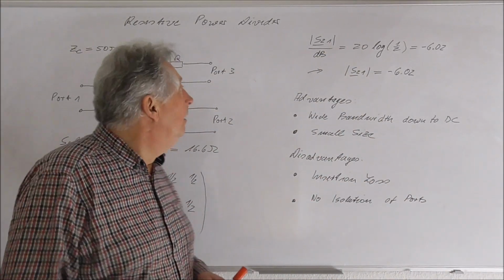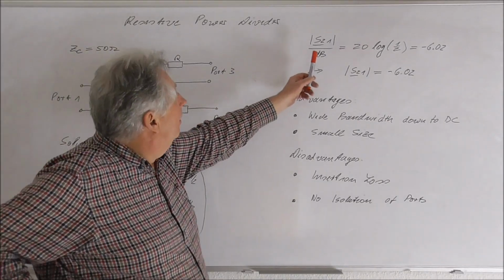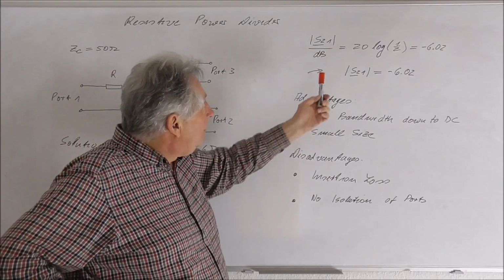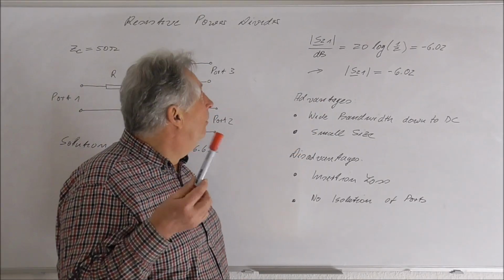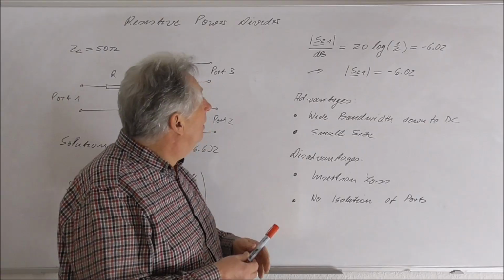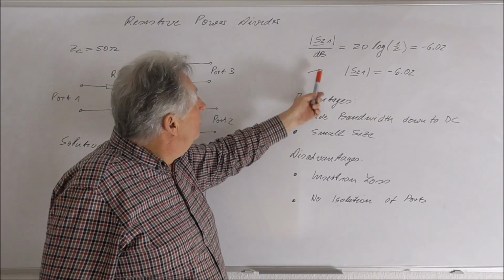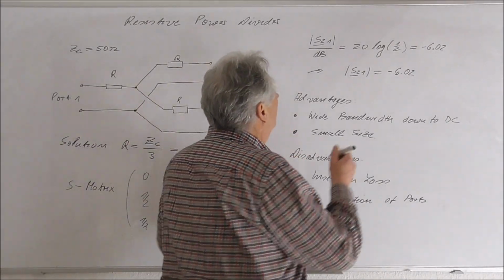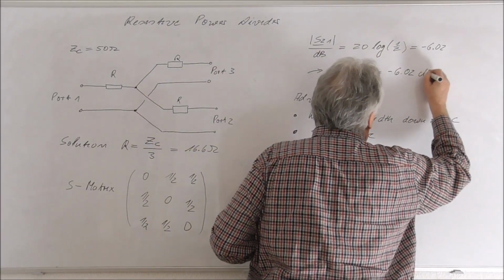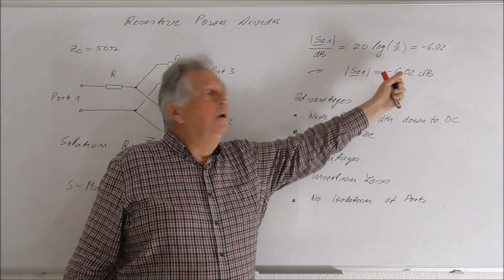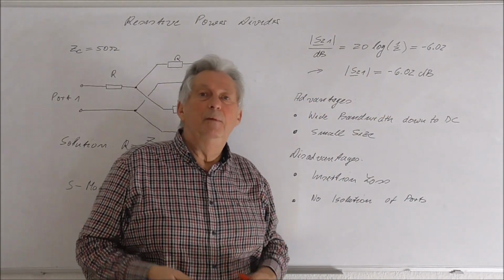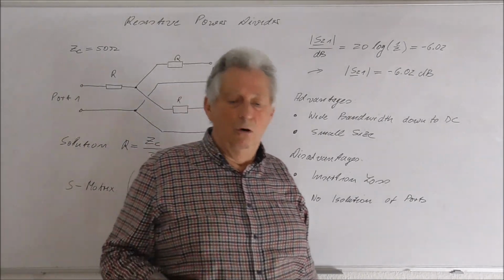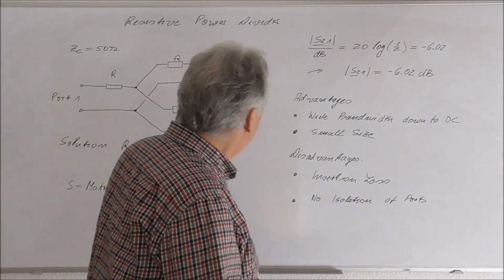And of course we can also give the parameters now in the dB scale, which corresponds to the diagram log mag in our network analyzer. If I change to the dB scale, then S21 is given by minus 6.06 dB. This means, of course, a resistive power divider will always show a certain insertion loss.